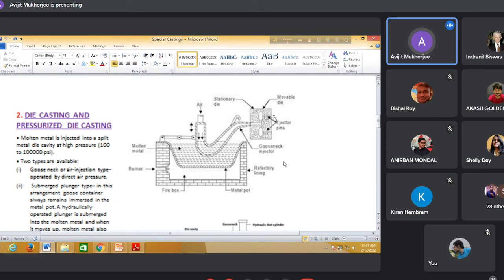So one die is movable, one is permanently fixed, stationary. Align these two dies previously, fill this pot with molten metal, bring the mouth somewhere here, and now apply pressure, or air pressure, and the metal will be forced to enter this cavity. So this is the mold cavity.